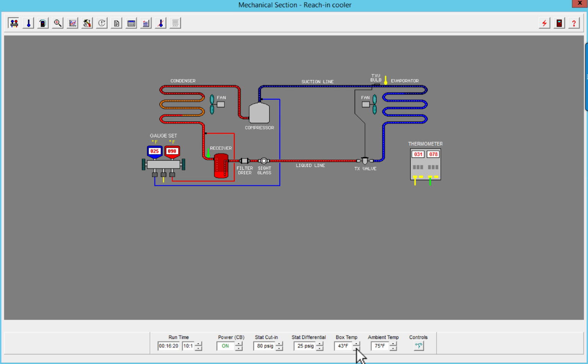Okay, my low side pressure is now down to 25 degrees, which is 62 psi. Okay, I'm really after temperature. So my low side is now down to 25. So I have a 6 degrees superheat, which is not good because I'm sooner or later going to start returning liquid refrigerant to the system.